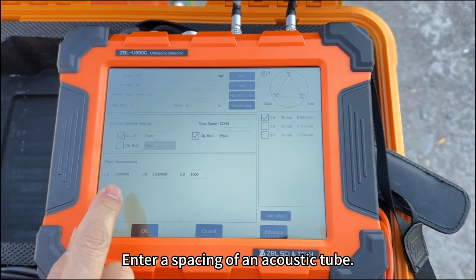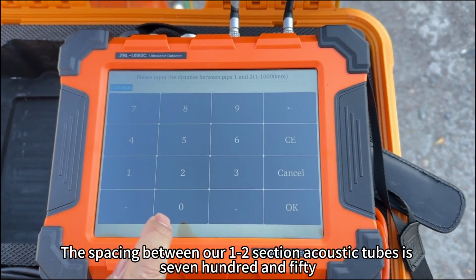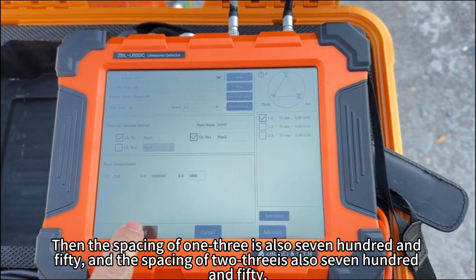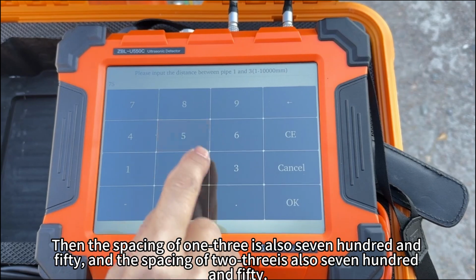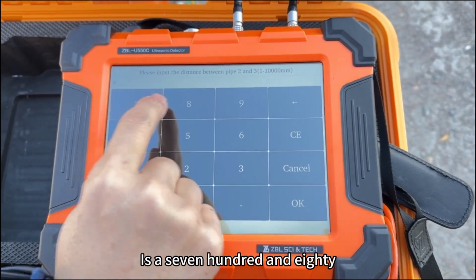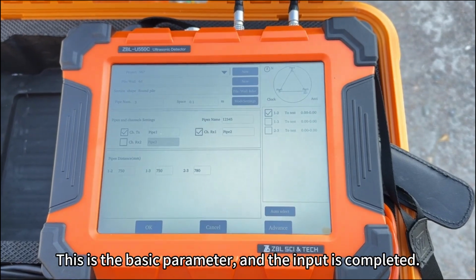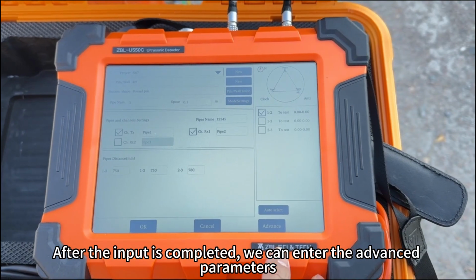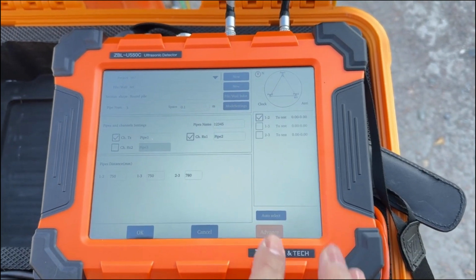Enter the spacing of an acoustic tube. The spacing between our section 1-2 acoustic tubes is 750. Then the spacing of 1-3 is also 750. And the spacing of 2-3 is also 750. This is the basic parameter. After the input is completed, we can enter the advanced parameters.